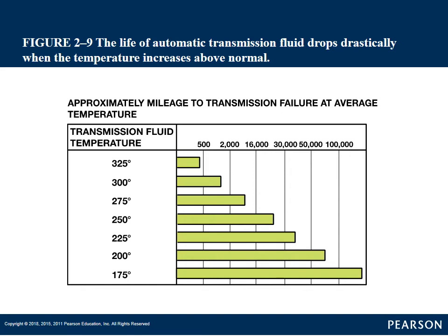They're saying you can get up over 100,000 miles before you have to change the transmission fluid. But as that temperature increases, you can see where they start telling you you can have failure of your transmission fluid if you don't service it at a much lower mileage. That's why vehicles that tow a lot, you want to put them on a shorter maintenance interval for servicing their transmission.